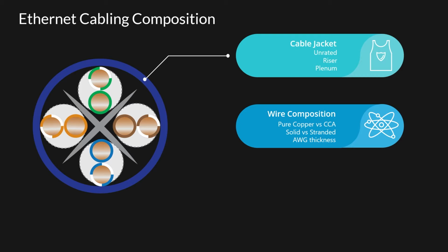It doesn't conduct signal as well over distance, and that's why they make the solid cabling, because when you've got the option to install it in some place where it's never going to move, then the solid is the better option. So when we're talking about Ethernet cabling to put into your building and wire into the walls, then you want that solid cabling. When you're talking about patch cables, just buy your patch cables anyway. But if you need to run some sort of long custom one for whatever reason, then stranded cabling is the way to go there.